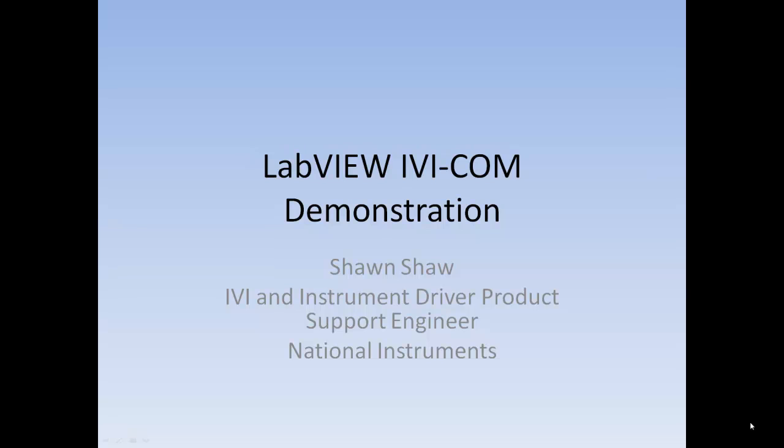IVI drivers make it easy to programmatically command instruments from numerous vendors. There are two different architectures that IVI technology supports, IVI-COM and IVI-C. National Instruments drivers are written utilizing the IVI-C architecture, but both IVI-C and IVI-COM architectures can be used with LabVIEW. This demonstration will illustrate just how easy it is to use IVI-COM drivers within LabVIEW.